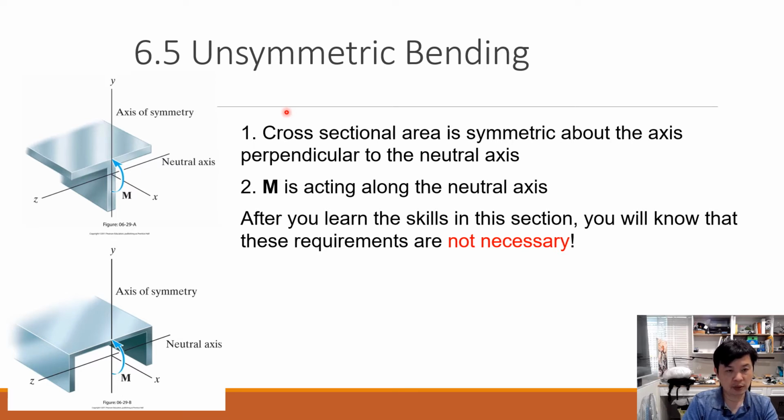First is your cross-section is not symmetric, or the other case is your bending moment is not along or perpendicular to your symmetric axis.